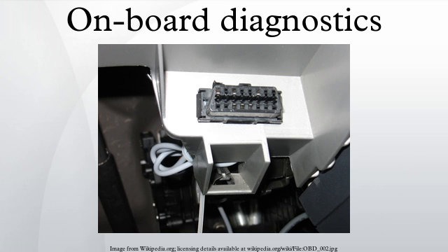All OBDII pinouts use the same connector, but different pins are used with the exception of pin 4 and pin 16. OBDII diagnostic data available. OBDII provides access to data from the engine control unit and offers a valuable source of information when troubleshooting problems inside a vehicle. The SAE J1979 standard defines a method for requesting various diagnostic data and a list of standard parameters that might be available from the ECU.